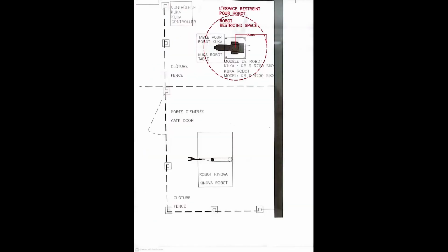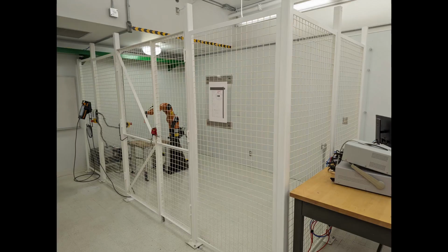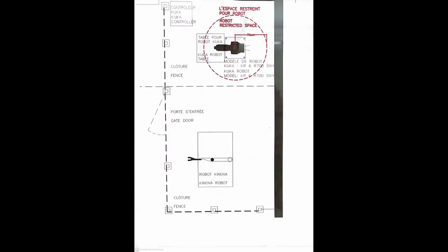Safety system. This includes a physical cage-like structure, a door state detection mechanism to detect whether it is open or closed, and 3 emergency stop buttons to further ensure user safety. These mechanisms work together to ensure that everyone in the lab is always at a safe distance from the arm when it is operating. Access within the cage is limited to certified personnel, and operating the robot program requires mandatory training to ensure everyone's safety.